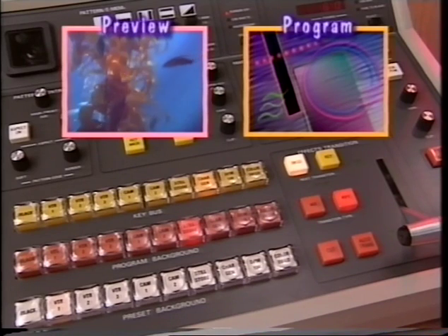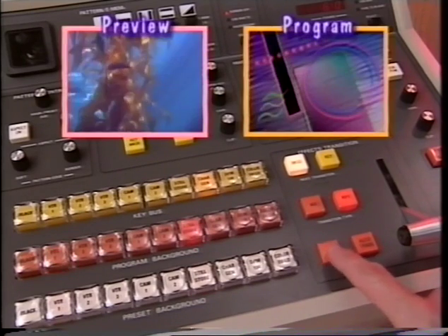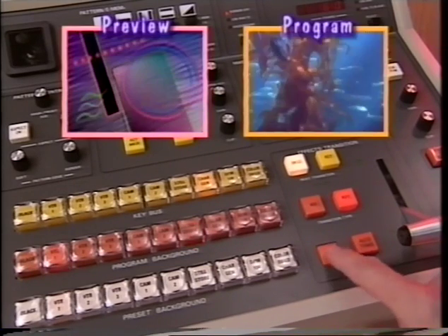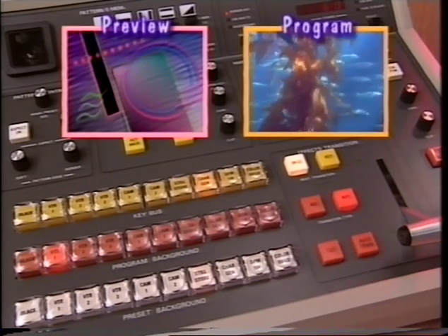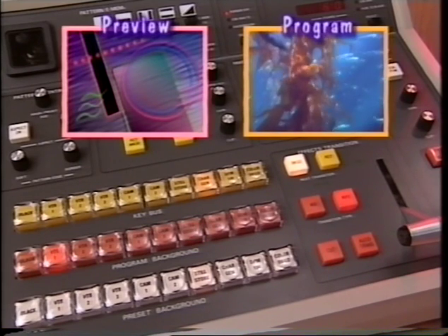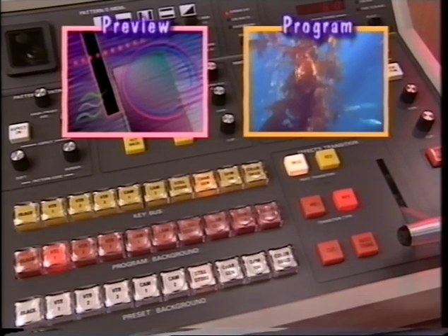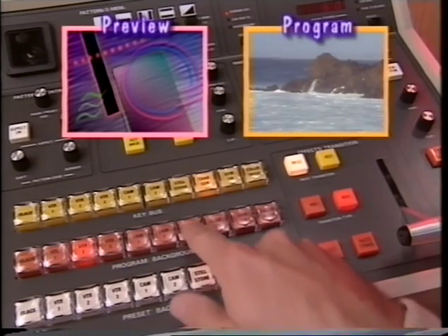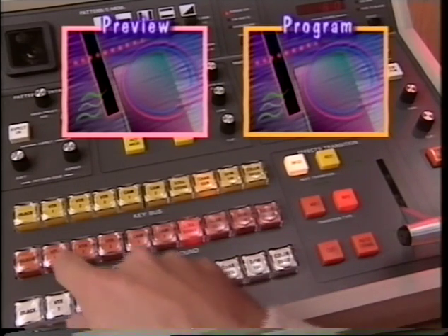The program source swaps positions and appears on the preset bus. Pressing cut again, the preset bus source will switch back to the program bus. A background cut can also be accomplished by simply selecting a new crosspoint on the program background bus. However, this method does not allow you to preview the new background signal.